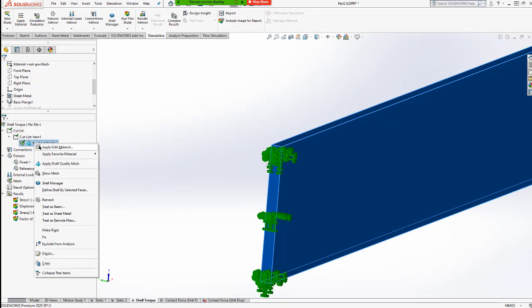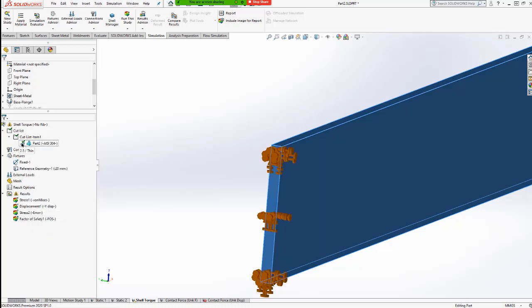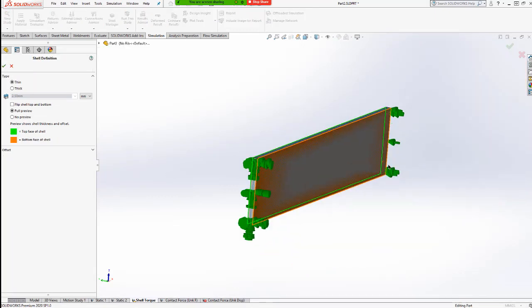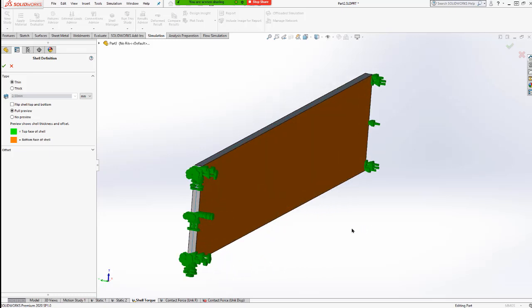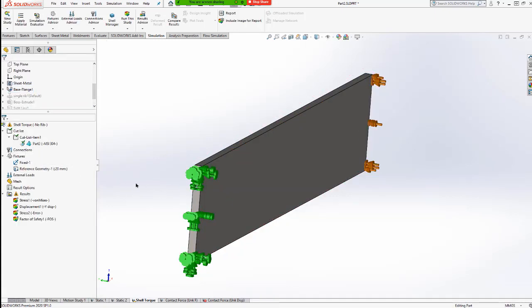Luckily, let's treat this as a sheet metal, and you can always just go to your part. Since this is a sheet metal part, we're going to have a cut list. I'm going to go down to sheet metal, and just to show it off, I'm going to edit the definition. Basically just choose our two sides to say, from this side to this side, we want this to be a thin of, I think it looks like I specified 2.5 millimeters. And it'll also ask if you want it mid-plane or bottom. We've always run with bottom. It's basically saying below the surface is where we want our part to exist.